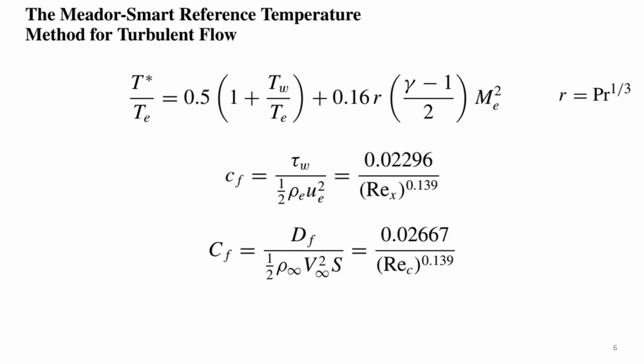Of course, this is a very approximate approach, so the reference temperature method can be used in preliminary design. In the phase of preliminary design of a flight vehicle or any structure working in incompressible and compressible fluid, the reference temperature method allows us to use incompressible equations, and with the correction in viscosity, we obtain compressible equations or compressible coefficients.